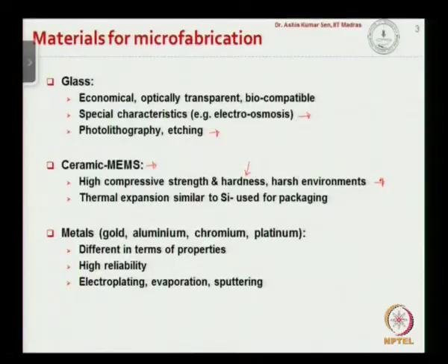And the thermal expansion of the ceramic materials is similar to silicon. So, many times the ceramic materials are used for packaging of silicon structures. So, the devices that are actually fabricated using silicon substrate are packaged using ceramic materials.